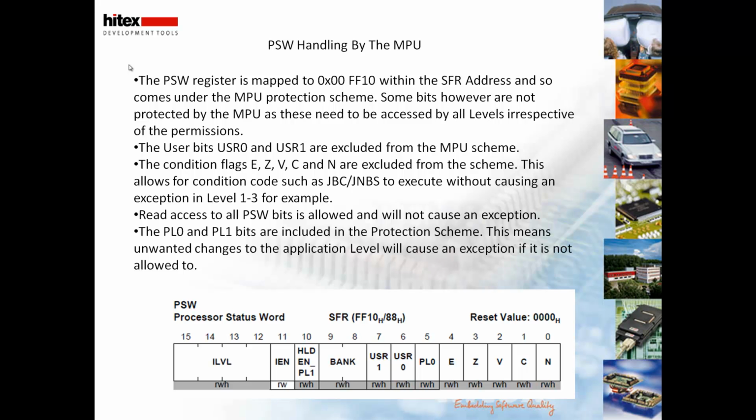It's actually a little bit awkward to change from one level to another level. So you have to use careful manipulation of the stack along with manipulations of the program status words to actually change from one level to another. So I've written a series of application notes, of which there are 4 or 5 in total, which basically show different ways of manipulating the information to change from one protection level to another.